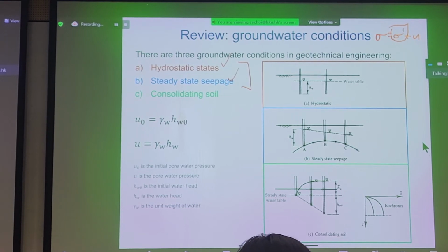It hasn't been disproven by anyone since Terzaghi came up with this concept. I'm talking about saturated soil mechanics, meaning your pores are completely filled with water, or they're dry. It's governed by effective stress. If you know this to be factual, then if you know the pore pressure, you must carry out effective stress analysis. There's no questions asked.